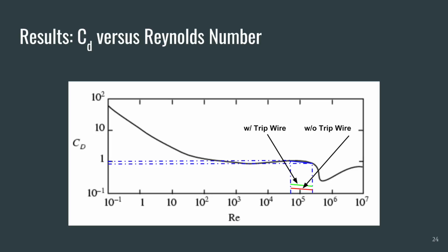See citation 7. The decrease in the coefficient of drag as Reynolds number increases in the regime of 5 times 10 to the fourth to 2 times 10 to the fifth was found in the measurements and is mirrored in the published plot. This supports the hypothesis that a more turbulent boundary layer has more near-wall momentum and replenishes this momentum faster due to the turbulent mixing action, allowing the turbulent boundary layer to exist longer in an adverse pressure gradient, which exists at the shoulder of the cylinder, and thus creating less drag.